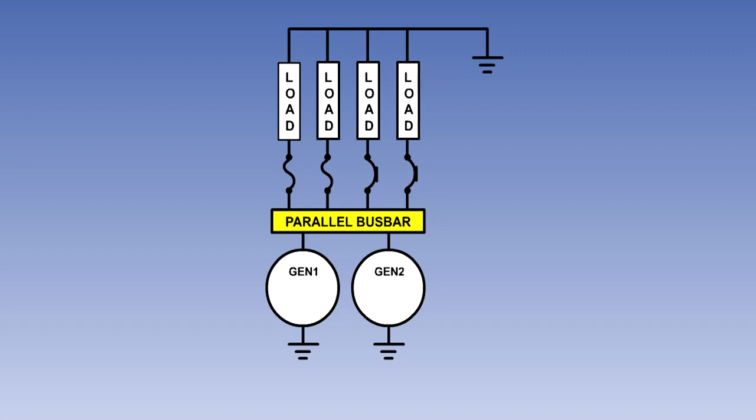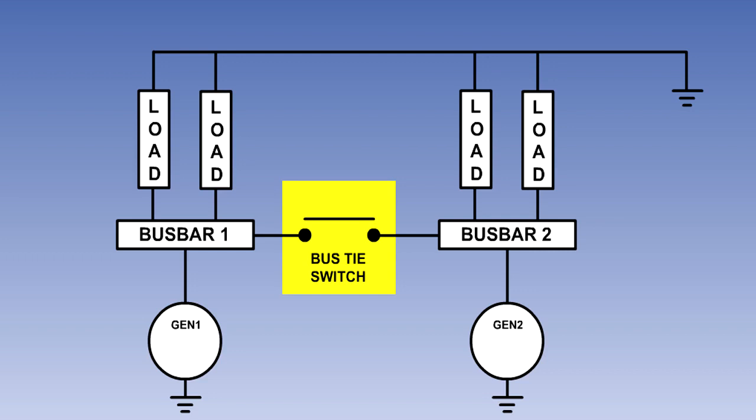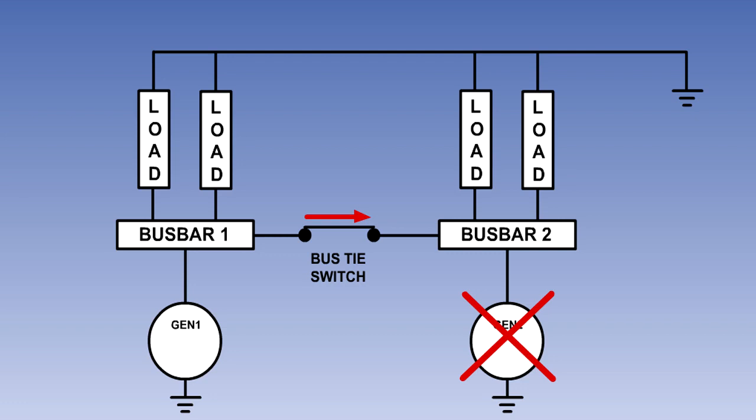In order to ensure the continuity of supply, generators or alternators can be operated in parallel, or switching systems can be incorporated to ensure that the loads of a failed generator or alternator are taken by a serviceable unit. Failed generators can be isolated from the distribution system.